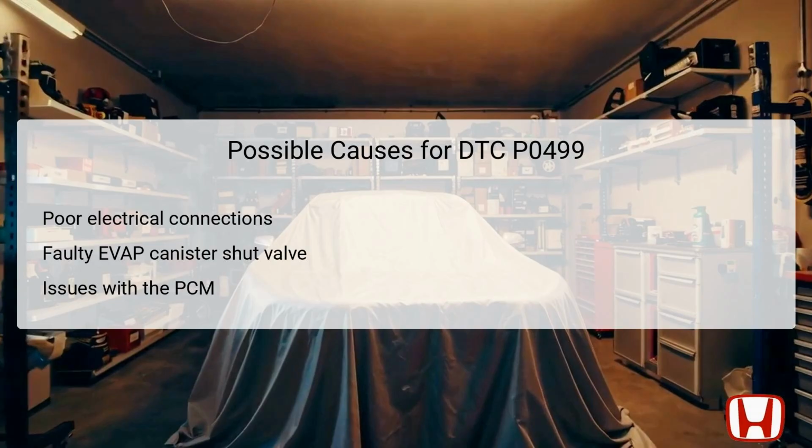Additionally, issues within the PCM can arise. If the software is outdated, or if the module is defective, it can mismanage the valve controls. Each of these factors requires careful examination to determine the root cause and ensure proper operation of the EVAP system.